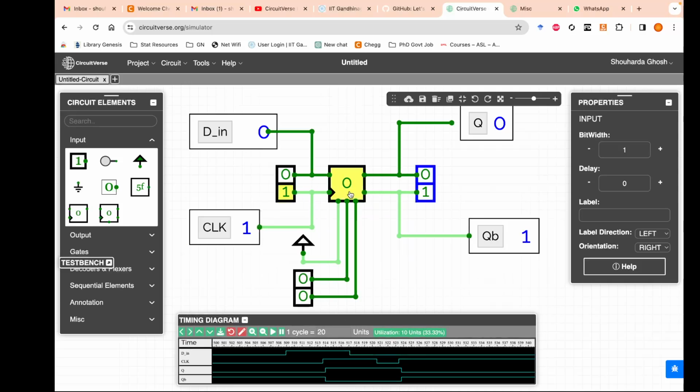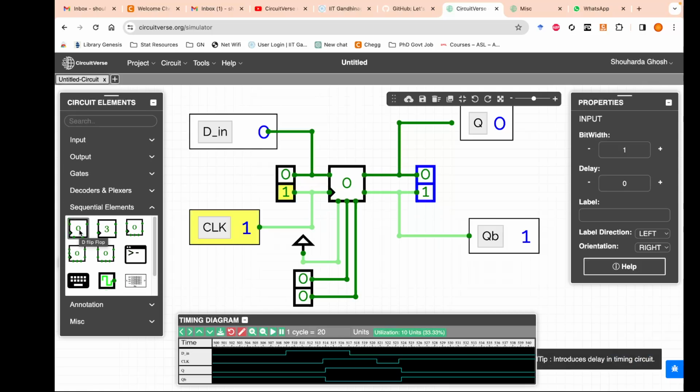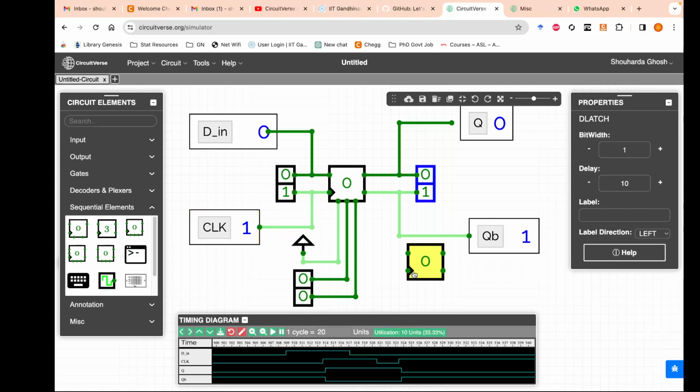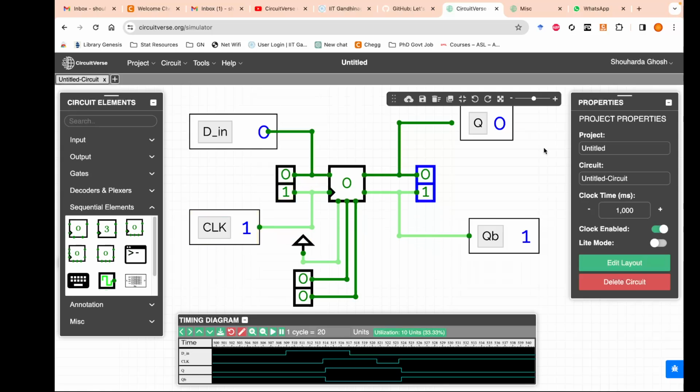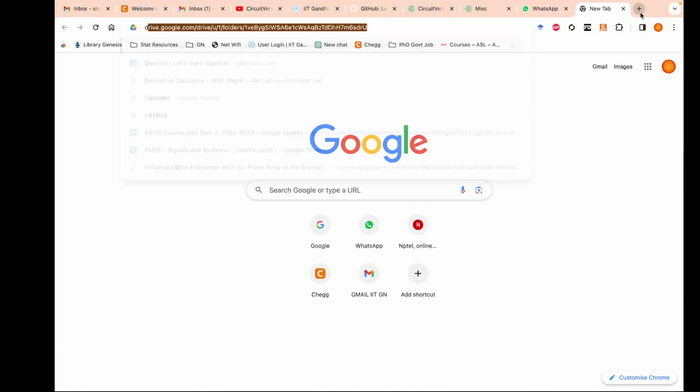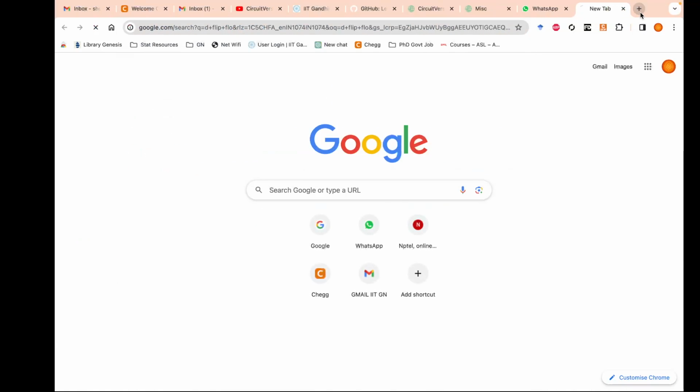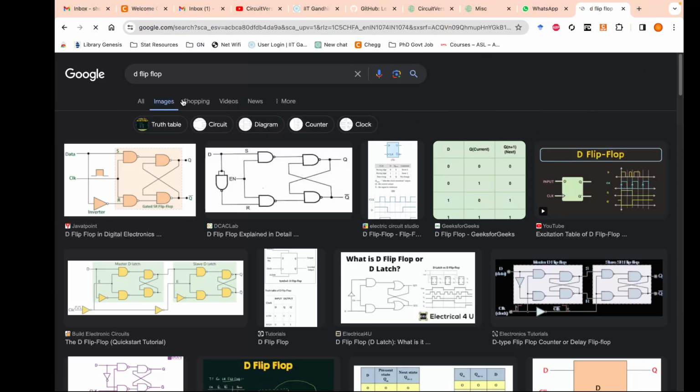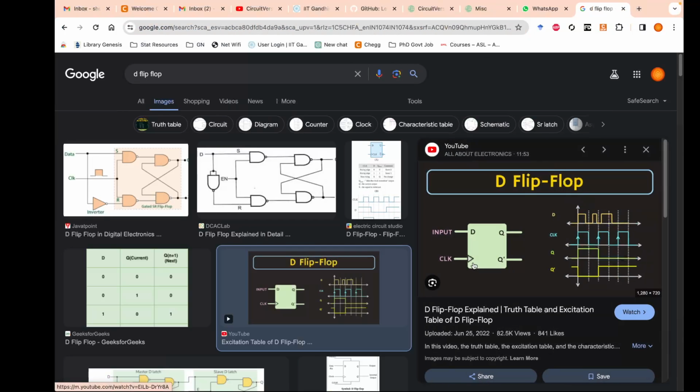So this is the rising edge flip-flop. Okay, this is the flip-flop. A flip-flop captures the value of the input at the rising or falling edge depending on the edge shown over here. This triangle actually shows that this is an edge triggered flip-flop. Although you will see a latch also having this triangle, that is not the case. If you actually look into circuit diagrams, let me show you the flip-flop. If you look at this D flip-flop, this is the triangle that shows that this is edge triggered.